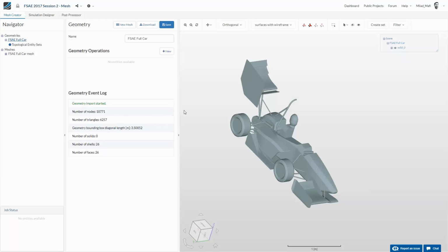And just because a lot of people are asking, what should I do if the car is not symmetric? If your car is not symmetric, for example, if you just have one radiator, like Zhang asked, you can't do a symmetric simulation. Or you have to be aware of the simplification and evaluate it before, like Brandon explained.